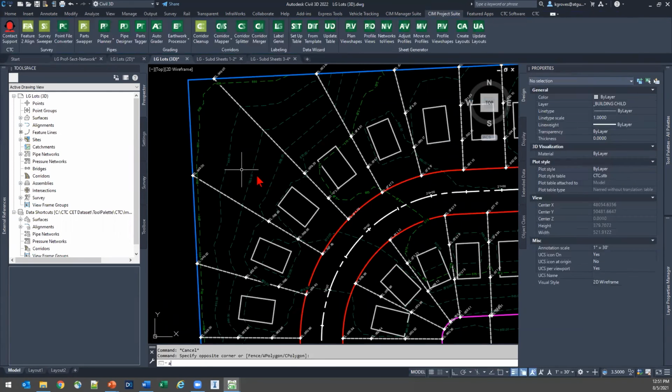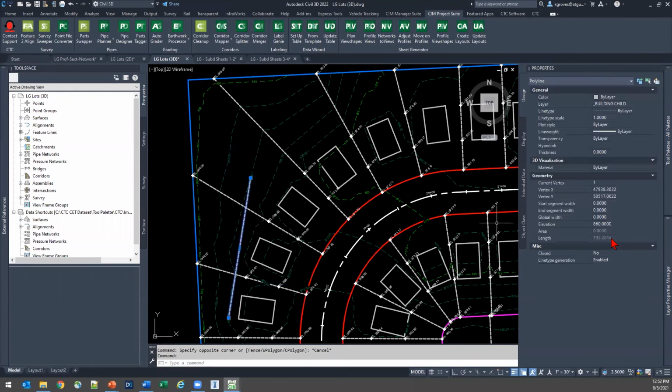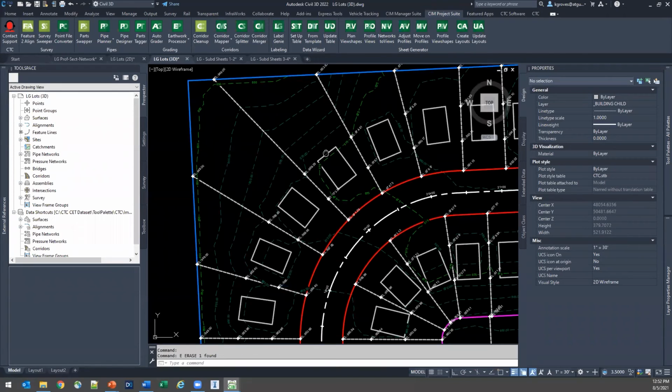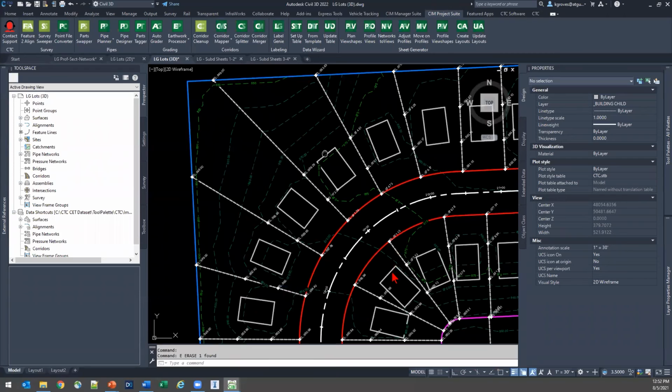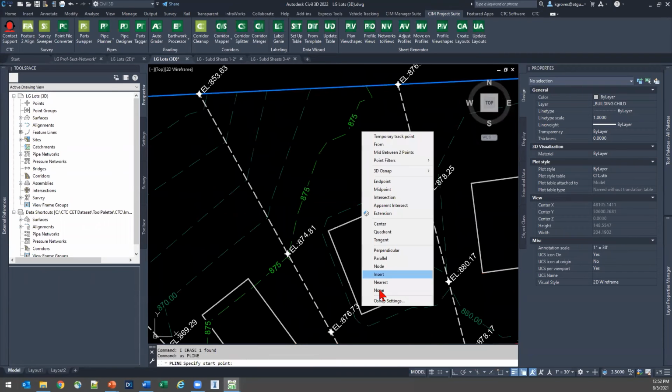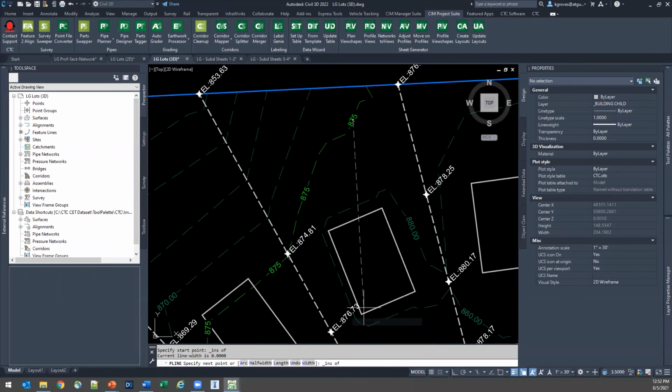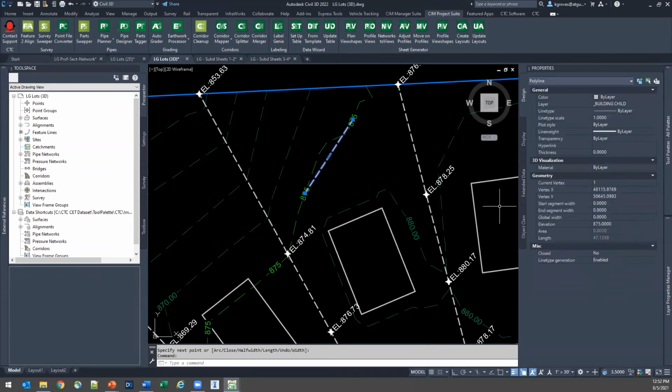If I draw a quick polyline, I'll go insert to insert. It's not going to be perfect because that's a curvy line and mine is simply a straight line. But that is just under 200 feet long. So that was every 200 feet along that particular contour and every 50 feet along my major. Yeah, it's about 47. So that's how the along interval works.